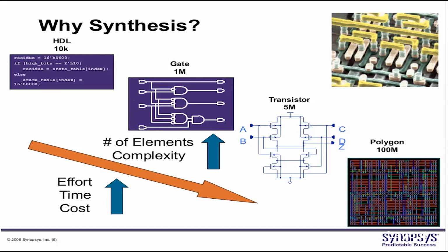Now, why synthesis? Why can't we hook up the cells directly? Let's assume you have to design a 3 to 8 decoder, like the example we saw. There can be two approaches. First approach: I know what a decoder looks like, what the logic circuit looks like. I can draw it on paper, then go to the library and choose the appropriate cells, hook them up, form the netlist myself, and then proceed through the physical design part.